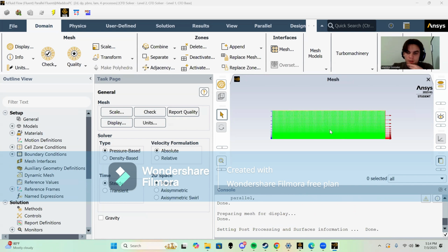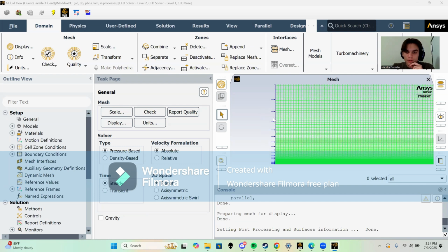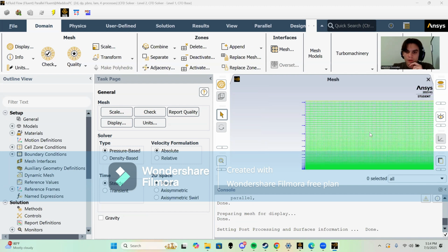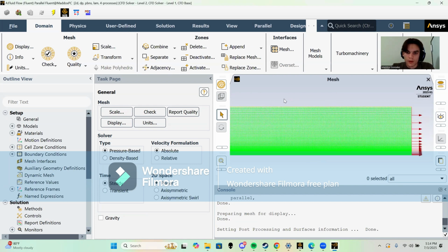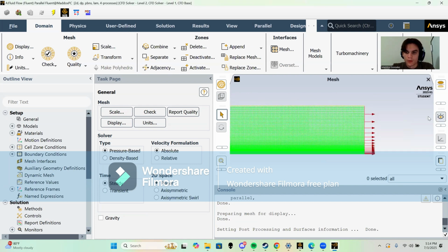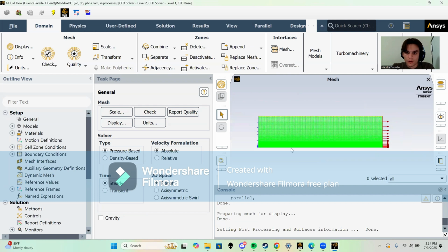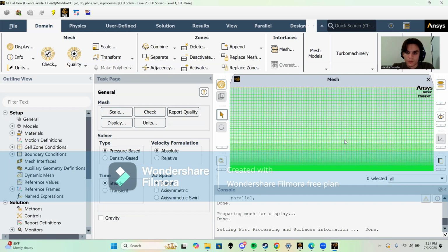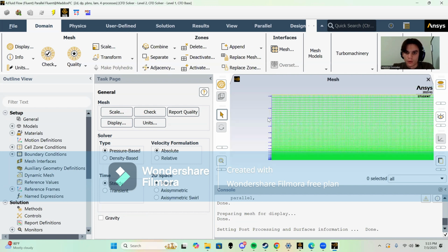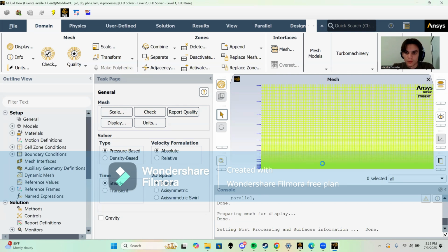All right, so our mesh gets imported into here properly. We know we labeled everything in the sketch and mesh settings because it correctly identifies that these blue lines are pointing inside the sketch, which says that this is our inlet. These red lines are pointing out of it, so that's our outlet. So we know we did that part right. Our meshing seems to have loaded pretty well, and we have exactly what we wanted. We don't have much detail in the top. We have everything down here in the bottom, the flat plate, which is where we're measuring anyways.